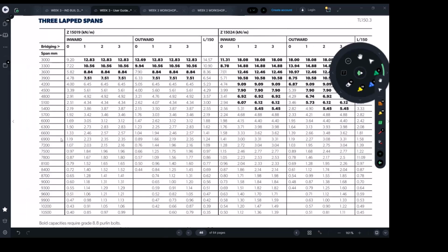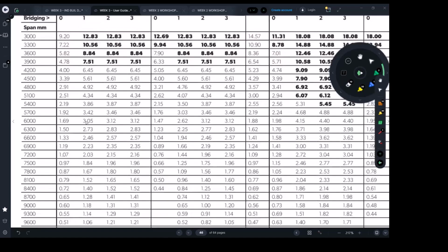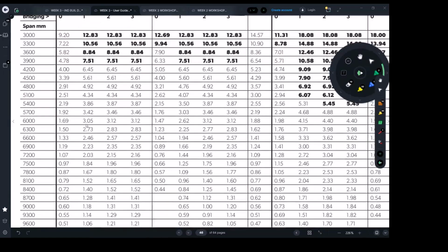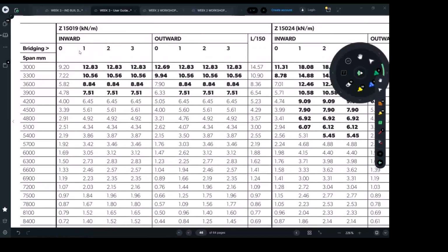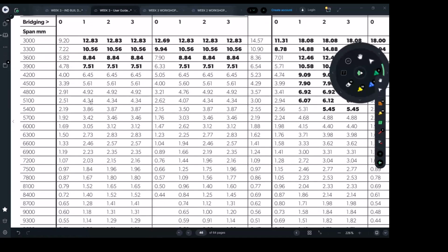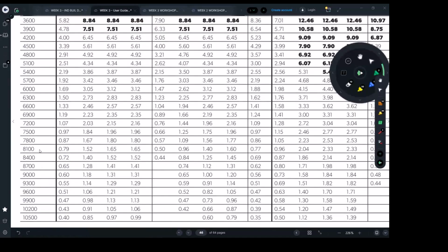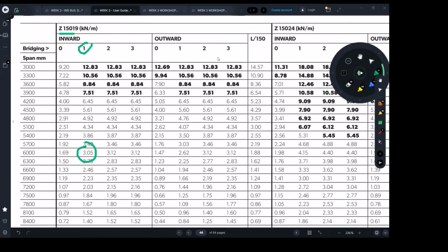3 kPa, 6 meters. Here we go. Yeah, we start sensing something. You start getting, you can use 150Z with 1.9 thick wall, the thickness of the base material. And you can say 6 meters can take 3 kPa here, right? You just need to use one bridging.